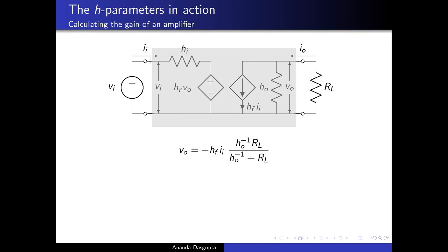Almost, except for the fact that VO has to be negative of that. Again, notice the current is being driven downwards according to our sign convention by the current source, which means the voltage drop it creates is higher on the lower side, less. So it's a drop when you go from bottom to top. But VO is a drop which you measure from top to bottom. That's the sign convention that we are using. That is why VO turns out to be negative of this voltage drop.